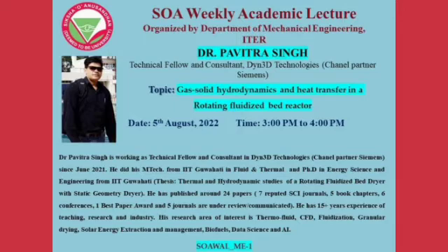And you can see this is the inlet of dimension 6 mm thickness, and this width is 50 mm. This is called the length of the reactor. So this is 50 and this is 6 mm, and this is the chimney outlet. This is a spiral chimney outlet actually. So this length is 70 mm and this is 50 mm. So this is the chimney outlet. So actually air is entering this reactor, creating a vortex and leaving this reactor by the chimney outlet, and solid particles will be in this location.